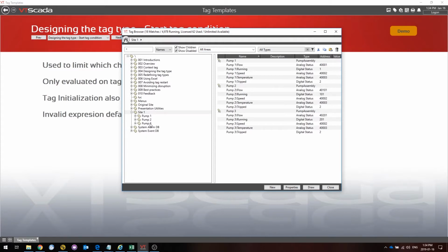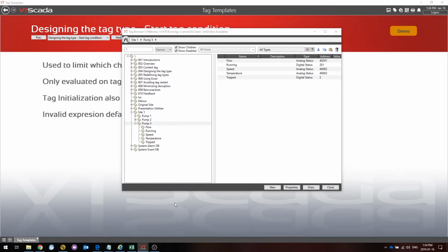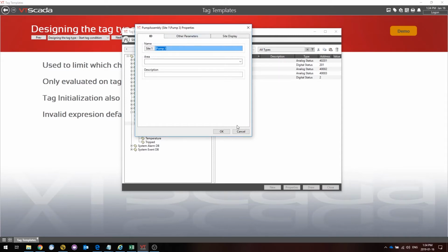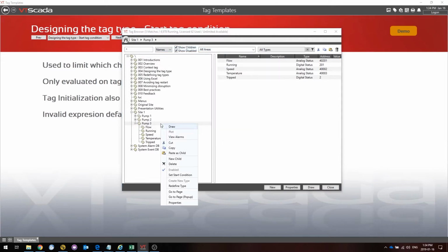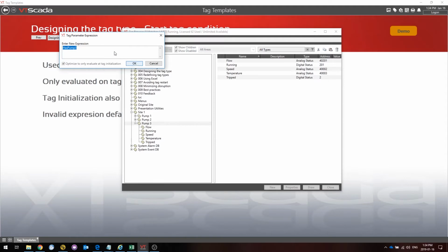Another way I could handle that, if I wanted to handle that invalid state, is we have another function called pick valid. And it'll make its way through to say, if has pump 3 is valid, use it. If it's not valid, use the next one. And that's set to a 1, which is always valid, so it'll default to 1 if someone hasn't set that.